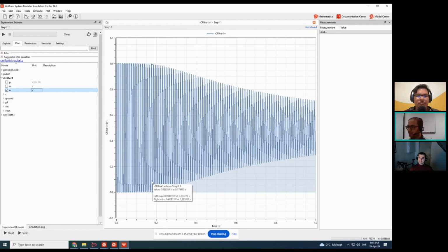This is the time series data. But in some cases, when you deal with music, where you're more interested in the frequencies, or you're doing vibration analysis, then looking at the time series data perhaps doesn't tell you the whole picture, or it is not easy to diagnose different things. And perhaps it's better to visualize the results as a frequency response.